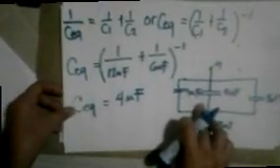Now, as we can see here, the 3 microfarad capacitor, the 11 microfarad capacitor, and the 4 microfarad capacitor are connected in parallel. So to find the equivalent capacitance, we use equation 7. That is, C equivalent is equal to C1 plus C2 plus C3.